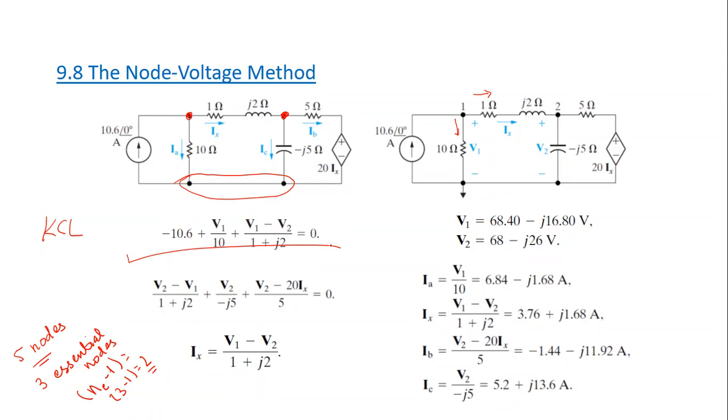Yes. Okay. Now let's write KCL to node 2. And again, I need to express the 3 currents related to node 2, the currents going away from the node. Here I don't have any current sources, so I will use Ohm's law, and I will start with this current that is going in this direction.